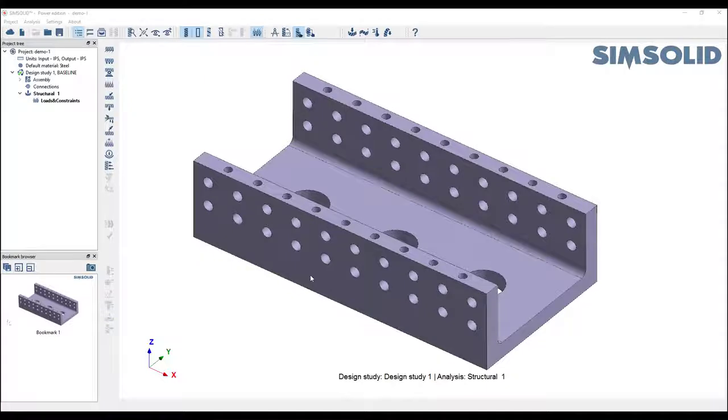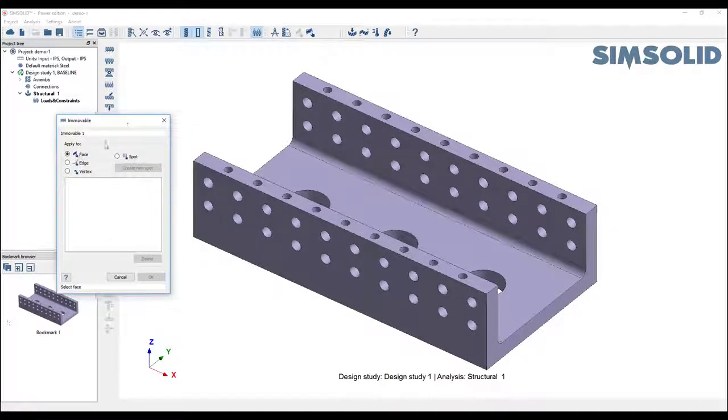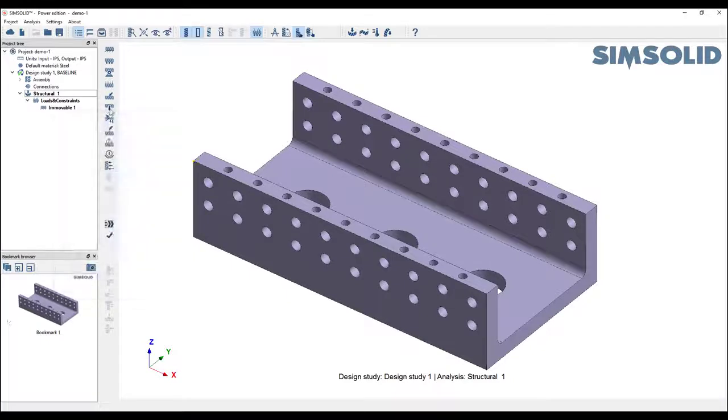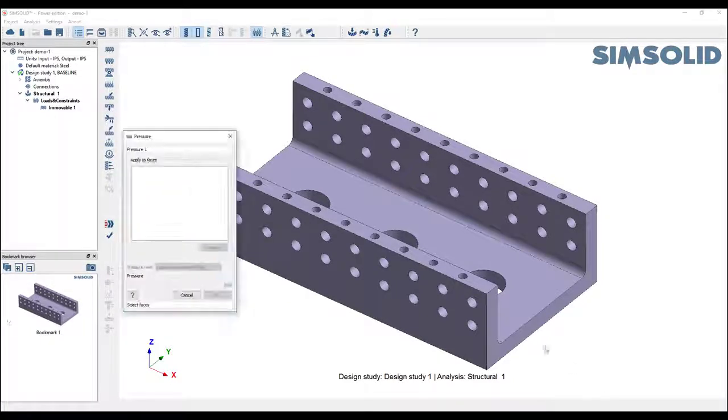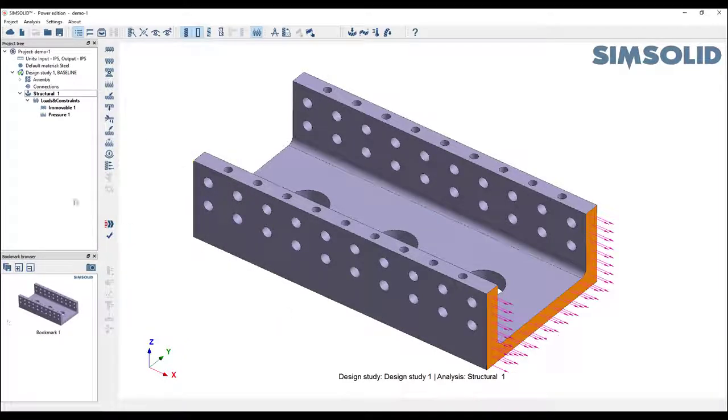Okay, let's take a look at how this check rigid motions tool works. Let's first take a very simple model and insufficiently constrain it. So I'm going to take this model and I'm just going to pick a single vertex, that point right there. Maybe I'll add a load here, but we're not going to use that. I could try to analyze this, but before I do, let's do the check rigid motions right here.